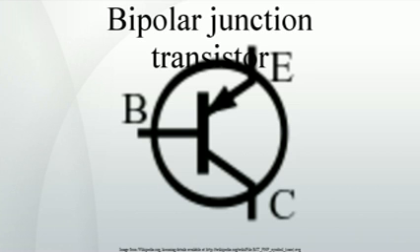The bipolar junction transistor, unlike other transistors, is usually not a symmetrical device. This means that interchanging the collector and the emitter makes the transistor leave the forward active mode and start to operate in reverse mode. Because the transistor's internal structure is usually optimized for forward mode operation, interchanging the collector and the emitter makes the values of α and β in reverse operation much smaller than those in forward operation. Often the α of the reverse mode is lower than 0.5.